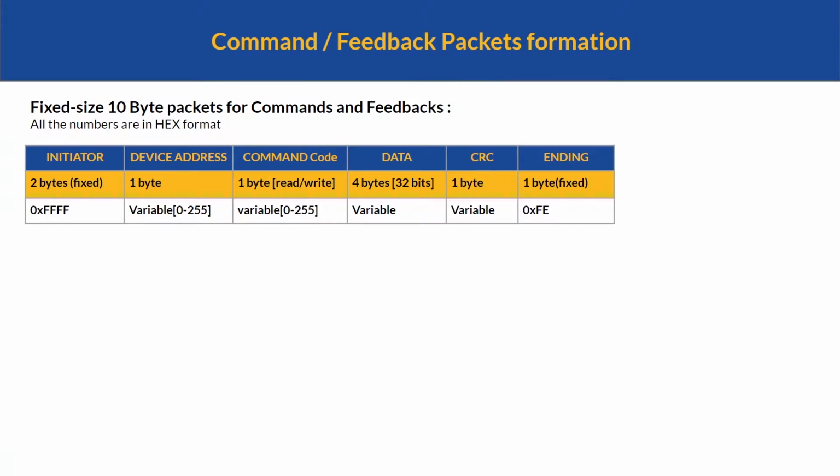Now I'm going to talk about how to actually form a packet to send, or how to interpret a packet that comes back from Solo. But before that, you need to know all the packets we're talking about with Solo have a fixed size of 10 bytes. It doesn't matter if you're sending a command or receiving feedback, it will be 10 bytes in any case. And all of the numbers are presented here and also in the packet in hex format.